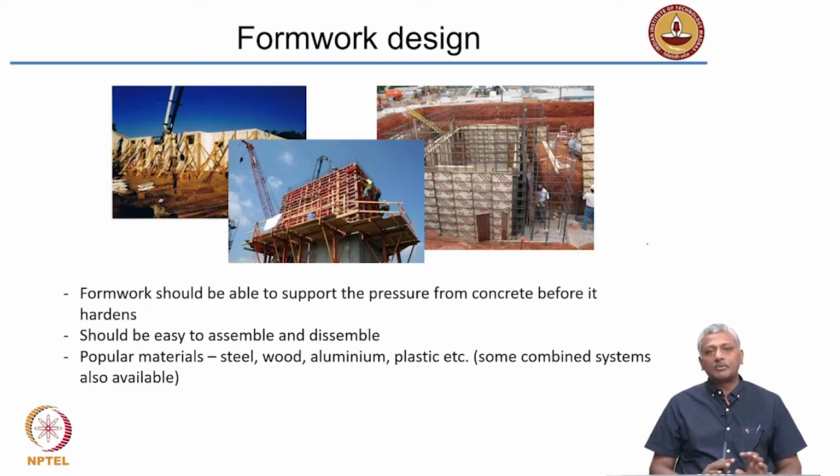We do not really worry too much about curved sections, but indeed there are several examples of construction where curved sections are also used. So, in such cases, you need to design the formwork appropriately with the right blend of materials. Okay. There are different formwork materials. In most of the job sites, you may see that the formwork materials are made out of plywood or other pieces of timber. Okay. So, in such cases, of course, you can imagine that the reuse is going to be limited when you use timber formwork, for instance.